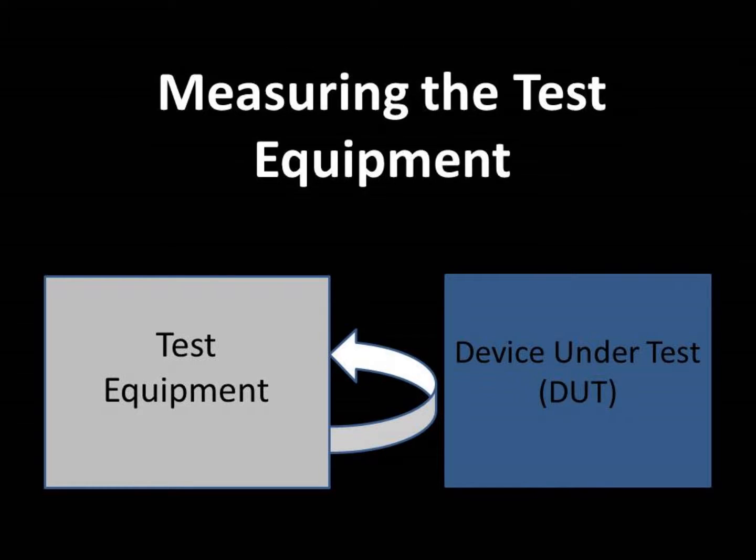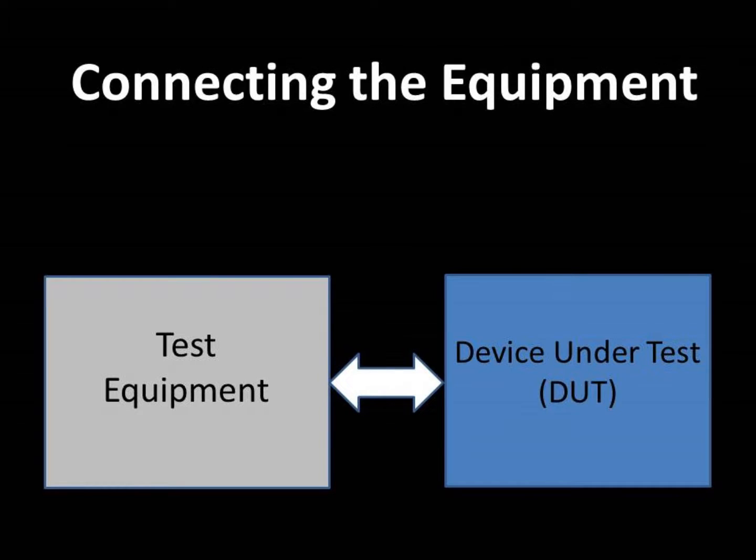One example of a common measurement error is to use a 10 picofarad scope probe to measure the switching frequency via the pulse width modulator oscillator ramp. The 10 picofarad capacitance of the probe is enough to significantly alter the results.